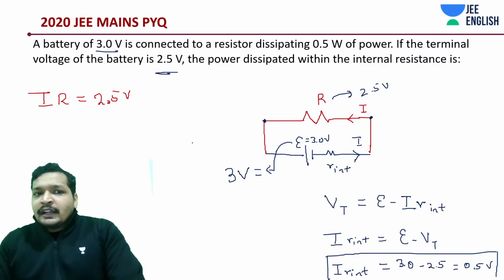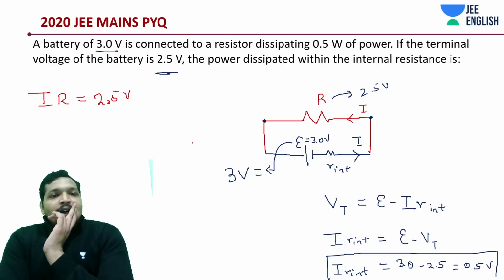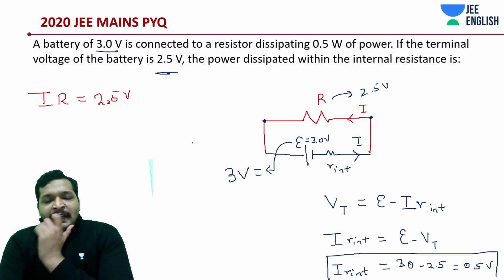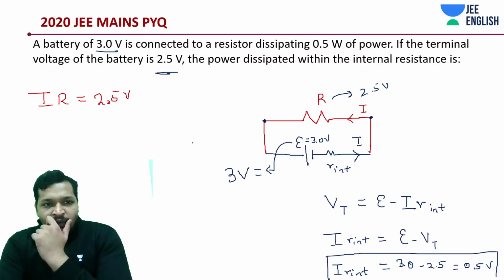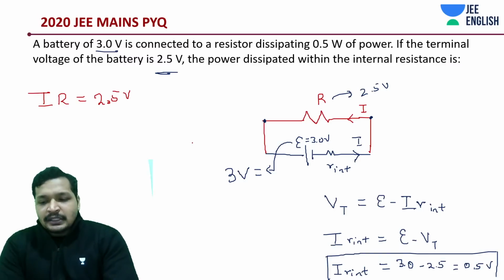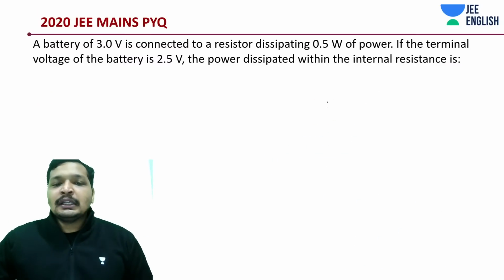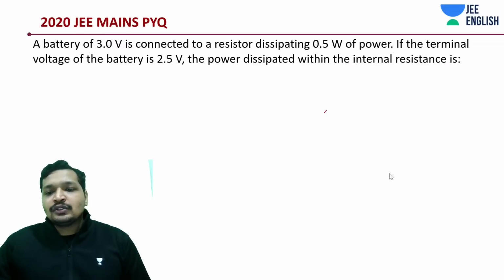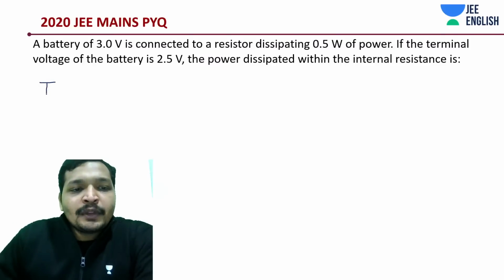Yes, I square R, you can do that, and you can calculate the value of I. The value of current would come out to be something like, I guess, 0.5 watt divided by 2.5. So that would be like what you're saying. It's like 1 by 5, 0.2 amperes. Okay, that is one of the ways of doing it. Definitely, yeah, you can calculate the value of current. So that's a good thing, I'll discuss that. You can calculate the value of current like this, right?